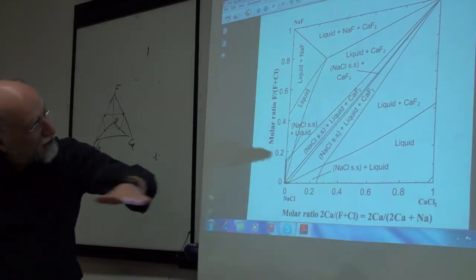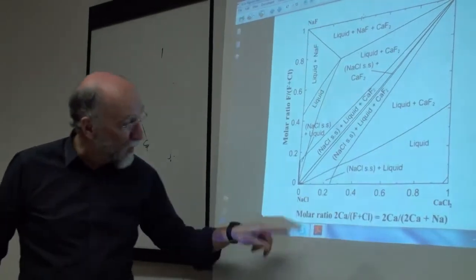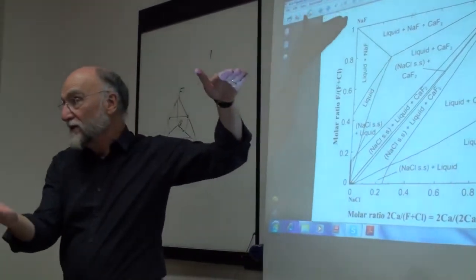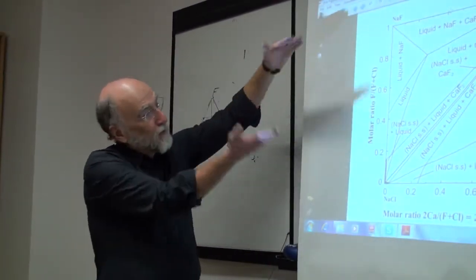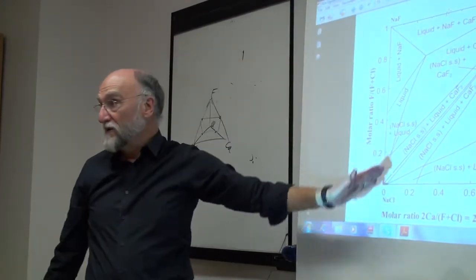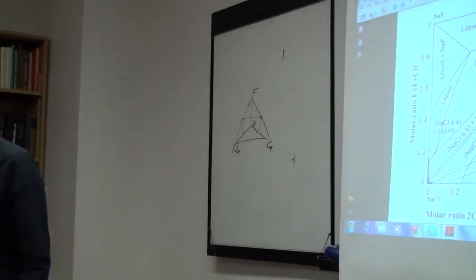If you were to draw a vertical section here versus temperature, this edge of the diagram would be the NaCl-CaCl2 phase diagram. If you were to draw this with a square prism with the temperature going up, each face is going to be the binary phase diagram. This obeys all the rules of ternary phase diagrams. You have two-phase regions, and a one-phase region for pure liquid here. You see the four lines come together at the nodes, these are all zero phase fraction lines. It's a standard section with three-phase triangles, and two phases with tie lines. The lever rule applies because all phases are in that system. It's very much like a ternary isothermal section. It's just plotted differently.